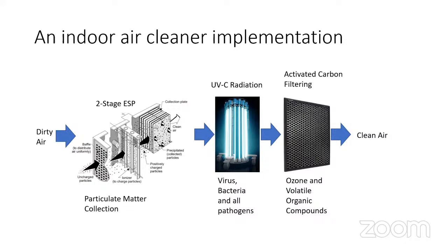I joined late. One question only: whether two-stage precipitation has been implemented anywhere at pilot scale in any plant? No, sir. This is basically for indoor air cleaning application only. We had done a study for implementation of two-stage for indoor air cleaning application. We found that the PM10 and PM2.5 concentrations are significantly coming down using these.